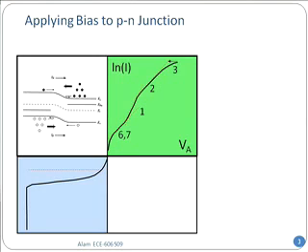And then it doesn't really look like the forward bias current, because the forward bias current is shown here in the green region, and it has its characteristics which are not reflected in the reverse bias, the ash colored region. You see the current first increases, it remains almost flat for quite a bit, and then all of a sudden, without any apparent cause, the current simply becomes very, very large.